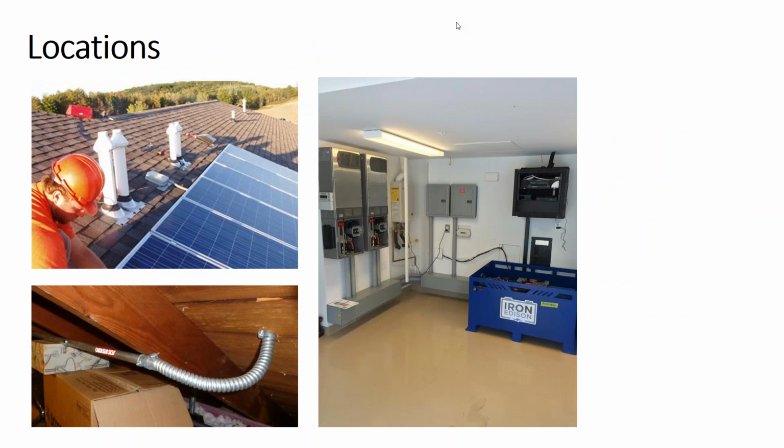So you don't want to neglect your locations. Locations may seem a little bit obvious to you, but the problem is the equipment you deal with in the solar industry can give you a false sense of security. You don't want to neglect your environment. That might be a bit on the nose for a solar design program, but just because your solar equipment is robust and designed to withstand the elements, that does not mean that uninstalled components have the same weather ratings as installed components.